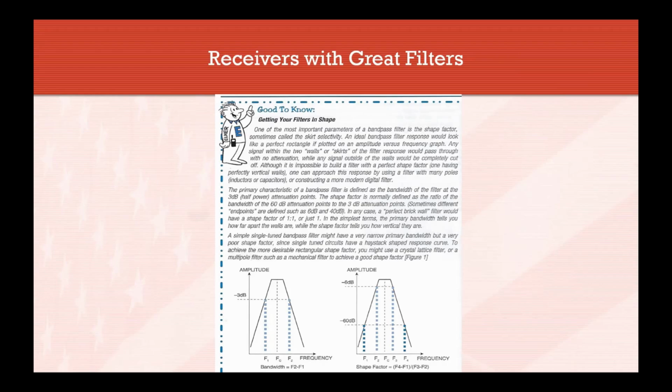We're tuned to get that center frequency right at the very center. And as that filter allows the signal to go up, the difference between the 6 dB and the 60 dB point is what determines the slope, or that which we use to get our decibel comparison on how effective that particular filter is.